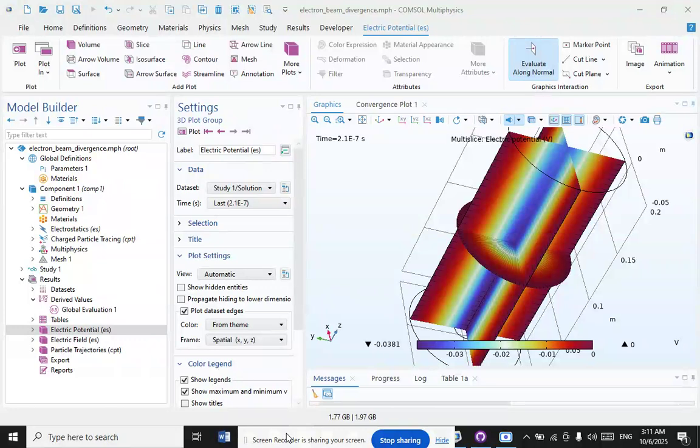The Charged Particle Tracing interface can use an iterative procedure to efficiently compute the strongly coupled particle trajectories and electric field for systems operating under steady-state conditions. Such a procedure reduces the required number of model particles by several orders of magnitude compared to methods based on explicit modeling of Coulomb interaction between the beam particles.